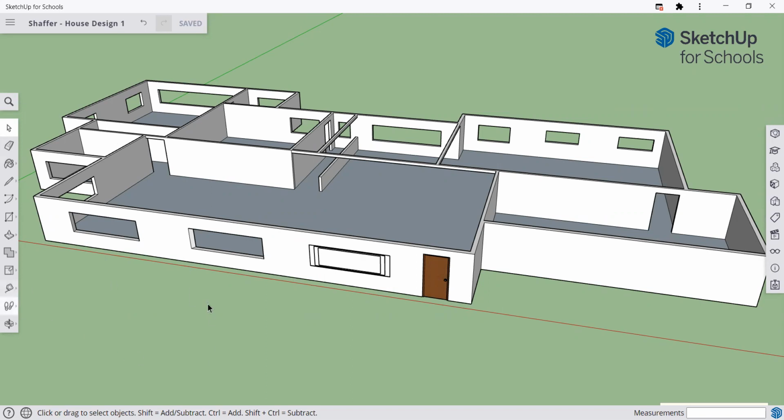Make sure that you're using the rotate tool. You will use the same method to move your door, sorry, if it had to go into an opening like this, where it's facing left and right rather than front and back. So make sure you're using the rotate, go back into the video, review those icons, how to use those tools, and that should have you set on how to place all your doors and windows into this assignment.